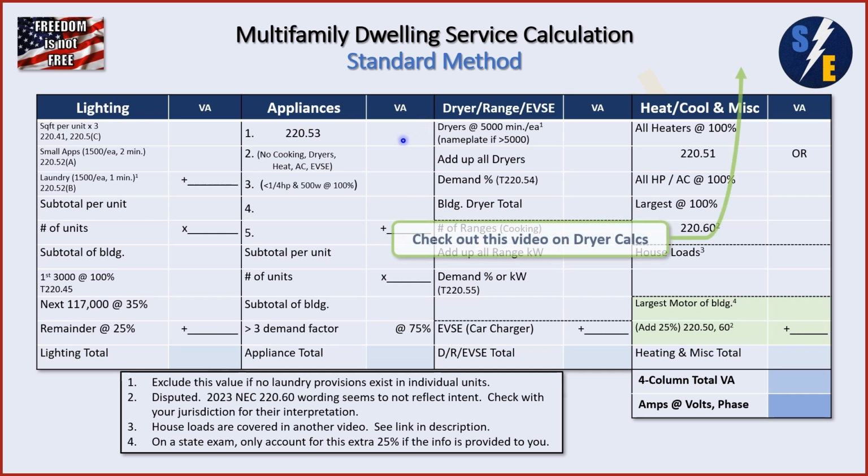We're going to start with our dryer. And please check out this video on dryer calcs for much more detail. We're going to add up all our dryers. We're going to apply a demand factor, and then we're going to come up with a dryer total.